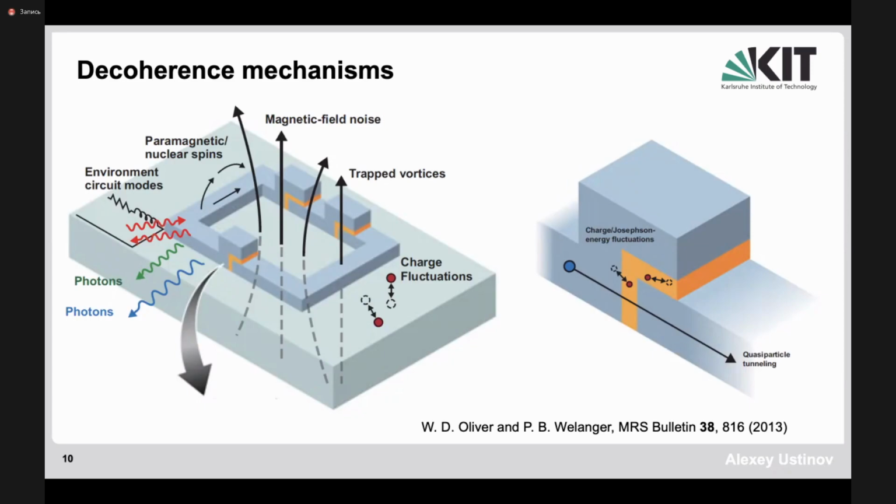So, all right, there are, of course, other types of noise sources which could be in the substrate. For example, if you have some phonons in the substrate, these phonons carry energy, and they can break the Cooper pairs and produce quasi-particles in the material, and quasi-particles will induce additional dissipation.